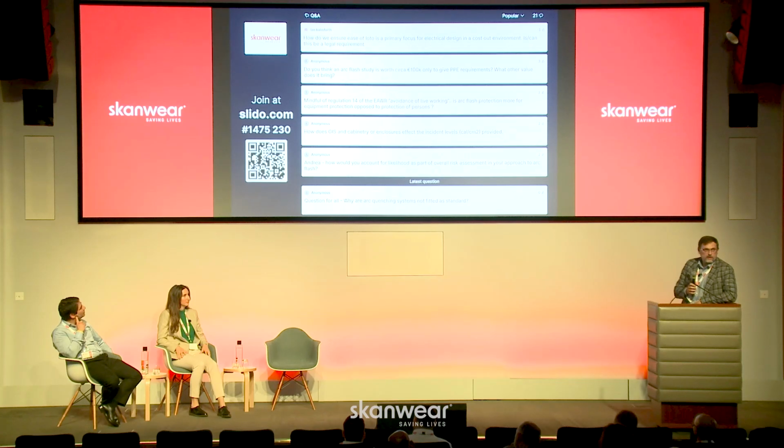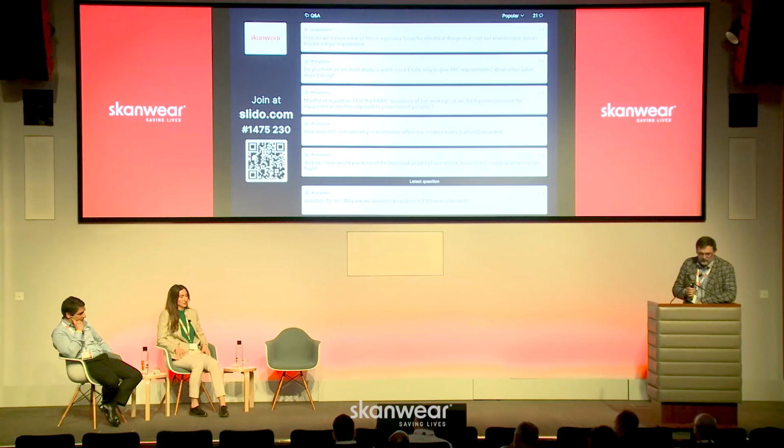I can add, it's not only output, and Andrea said it in the very beginning. An arc flash study is not only the PPE level, it's selectivity and equipment evaluation, short circuit, and arc flash, and sometimes even power flow if you need it. So this is a complex study of a few things. It can be super simple, but it is a power system study, exactly.